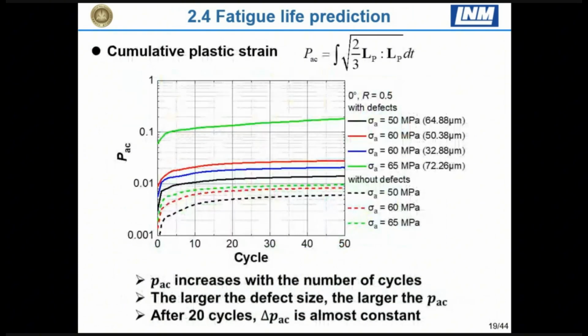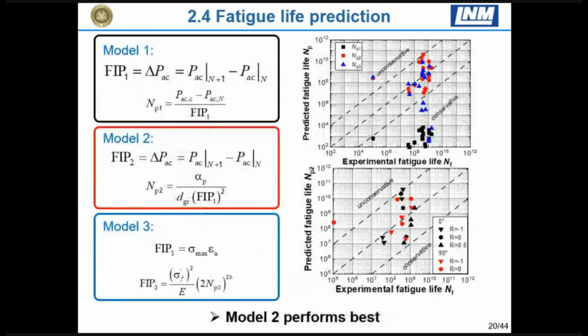And then we can see some kind of cycles. The accumulated plastic strain is quite stable here. We use this kind of fatigue indicator parameter to correlate plastic strain with fatigue lifetime, and we made the prediction using the method. Also, the results are compared with different experimental ones.